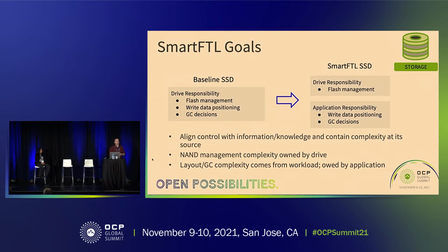And in a SmartFTL architecture, I'm proposing that the drive should still be responsible for all flash management. That's where the detailed knowledge of the NAND media and all of the required functionality for managing the NAND is. But I'm proposing that the application has a much deeper knowledge of where data should be placed and what the correlated lifetimes are, as well as potentially GC decisions.